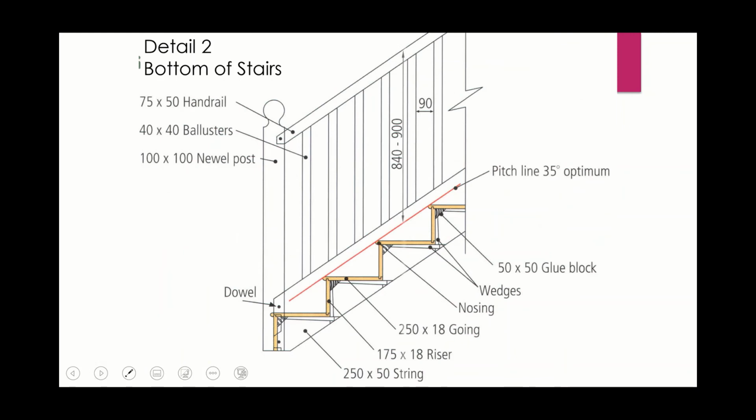And this is the drawing detail for the bottom of the stairs. Again, 1, 2, 3, 4 steps. You've got the wedges, glue blocks, balusters, newel post, handrail, etc. And it shows also the optimum pitch is 35 degrees.